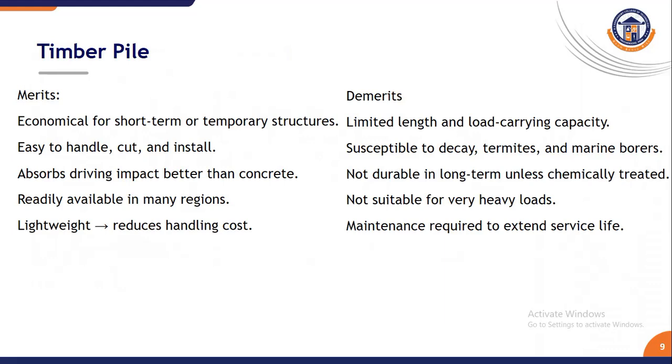But in the demerits, limited length and load carrying capacity occur in the timber pile, and it is also not durable in long-term projects and not suitable for very heavy loads, and the maintenance required is very high. So it's a main drawback for using timber pile in construction projects. So most engineers do not recommend timber pile for projects.